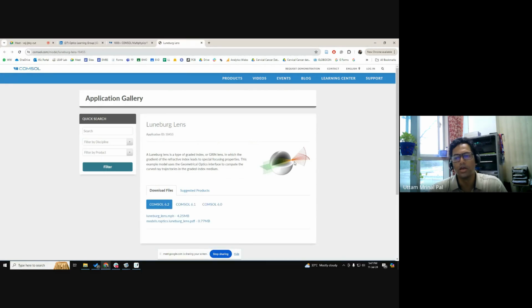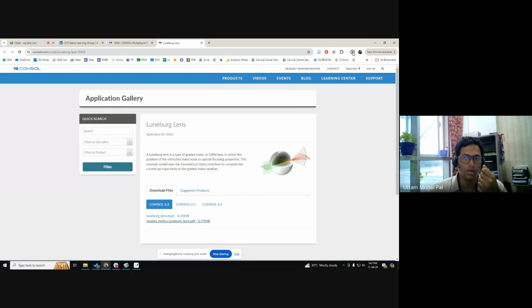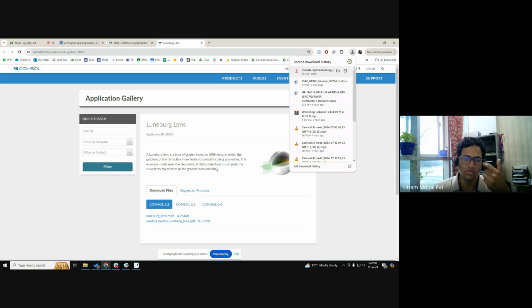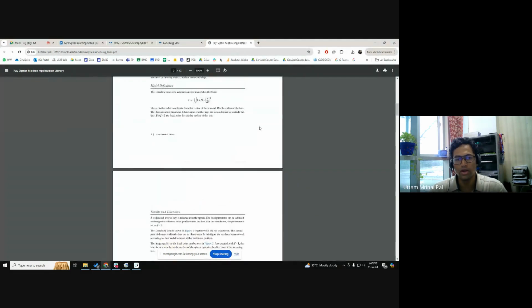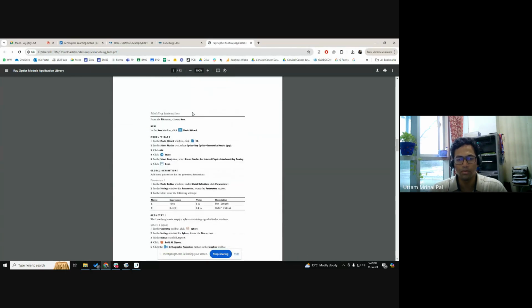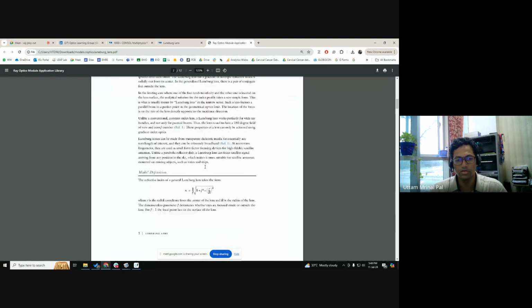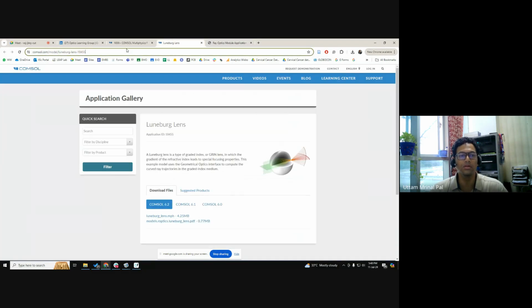Here, the refractive index is spatially varied across this domain. It's some kind of function that is written, right? So either you can write a piecewise linear function, or you can call a piecewise function. Here you can see the refractive index is like this. As you go radially outwards, the refractive index decreases. Okay, I will share this.